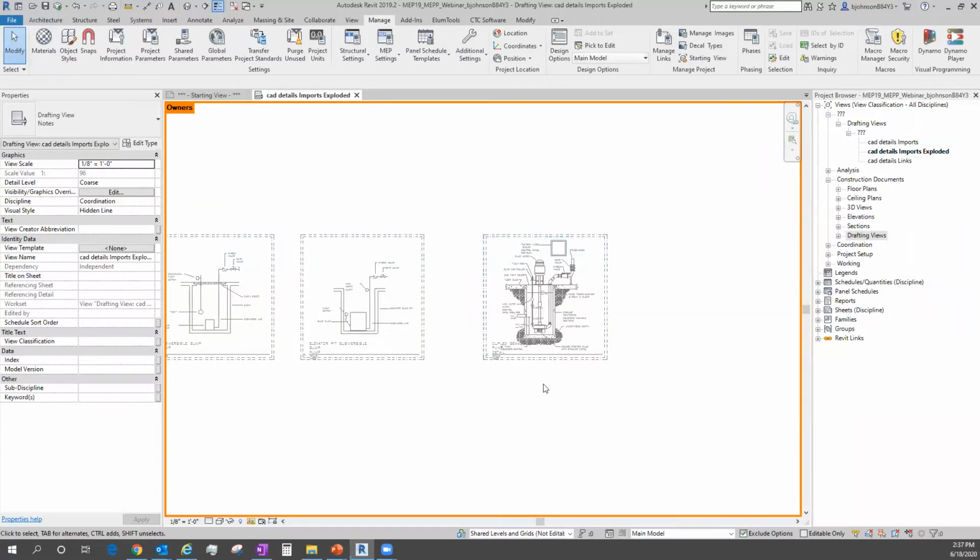This is not part of our standard. This is not how we do it. You always do that, but leaving it in a CAD file and linking it so you have the ability to do any kind of edits you want, but it's not actually truly a part of the Revit database at that point. It does kind of make a copy of it in Revit, so usually I don't like that linked workflow regardless. But if you've got absolutely no time whatsoever to turn it into a real Revit object, that would be the way I would do it, is to keep it in CAD.